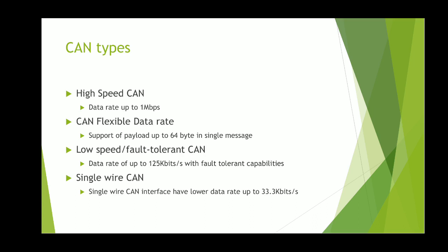In low speed or fault tolerant CAN, the data rate can reach only up to 125 kilobits per second, but it has some fault tolerant capabilities.